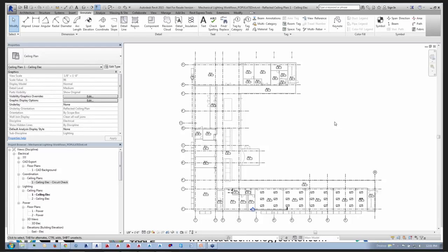As Nate said, we are going to discuss and demonstrate some workflow related issues and techniques that will make your lighting practices in Revit a bit easier, more successful, and more efficient. The main things I want to talk to you about today are reference planes, spaces, filters, and family clearance, and how these can all be configured and leveraged. We'll give some little demonstrations and walk you through how you might use these elements to make your Revit experience a little smoother and make it a more successful process.